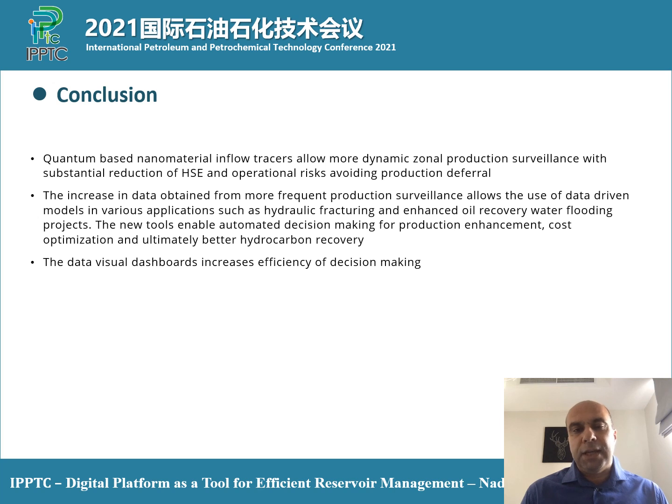So, in conclusion, we've seen in the presentation that the domain of inflow tracers is definitely giving a step change in production surveillance, where you don't need any intervention, substantially reducing operational HSE risks, and definitely enabling us to obtain more frequent data that can be used in physical and data-driven models or machine learning to improve or automate optimization of reservoir management.